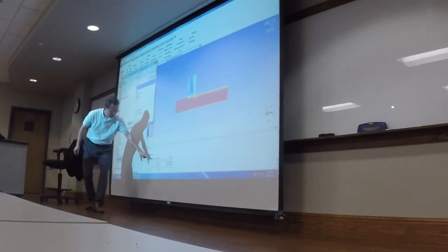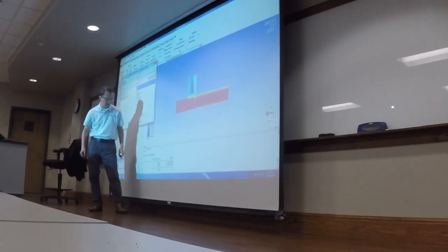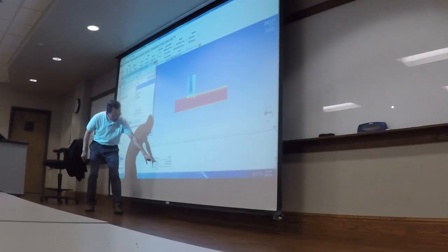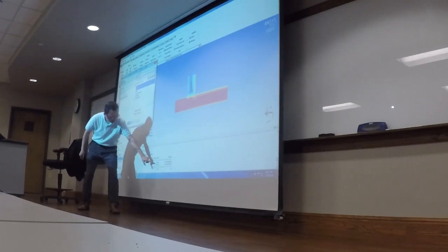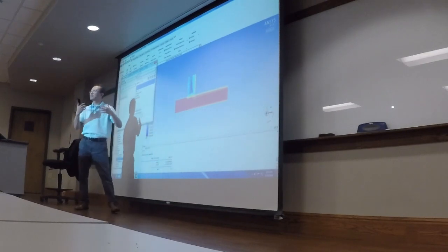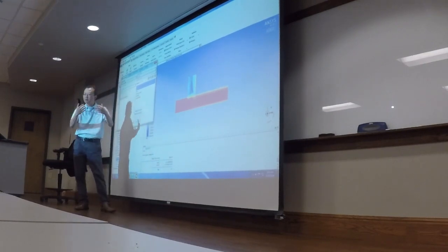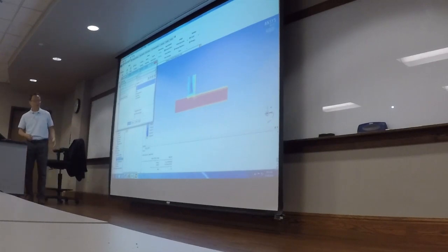All right. Now this is a screenshot I'm talking about. When you turn in your homework, I would like to see this. And so here, mass flow rate from exit 1 in terms of kg per second, about 95, and exit 2 only 5. So here, negative sign means it is leaving the domain. Into the domain positive, leaving the domain negative. So both exit. So this is what I would like to see. So our assumption is wrong. It is not a 50-50 split. Actually, for this particular case, 95 to 5.